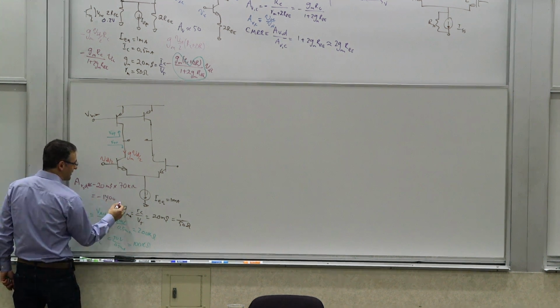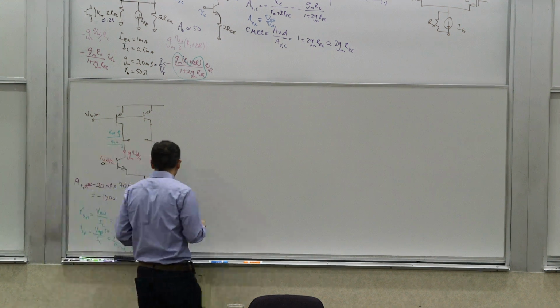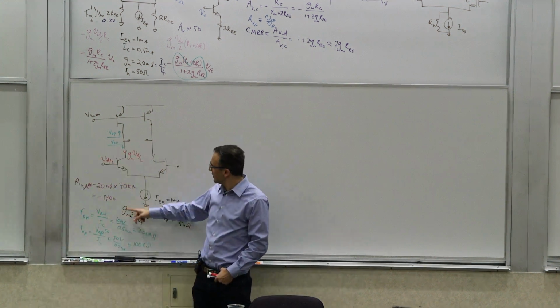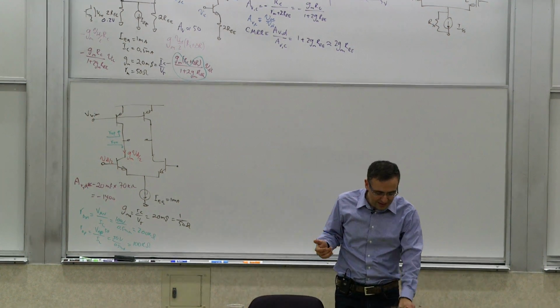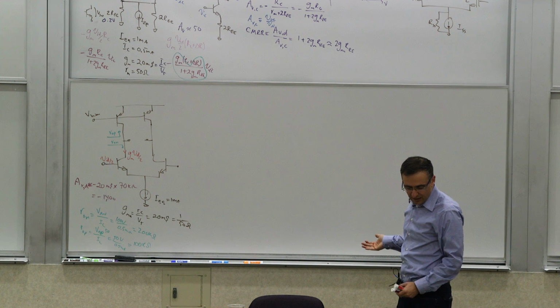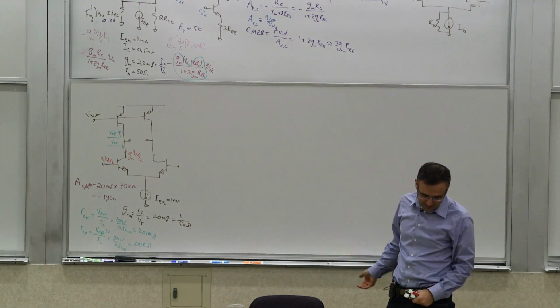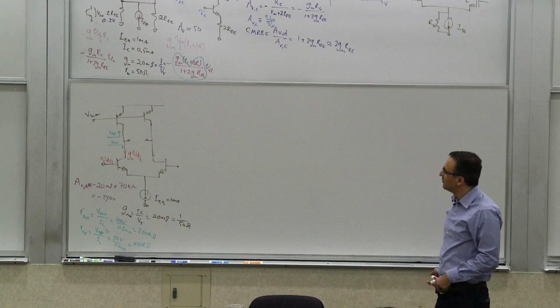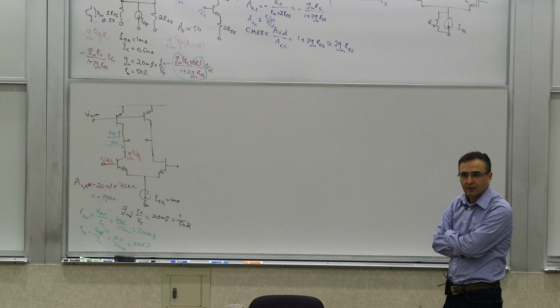You're at 1400 now. This is a substantially higher gain you can achieve with something like this. And if you were in MOSFETs, it would be less because then you get less gm for the same current, and we'll do the numbers with MOSFETs too. You will see, but you will still get higher gain than that. So that's basically what you get for this system. Now, that's basically taking the signal differentially, right, from the output.